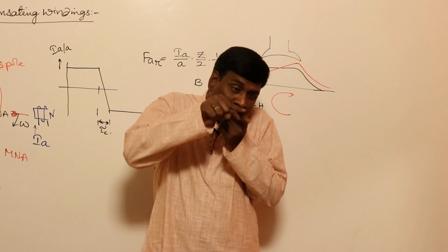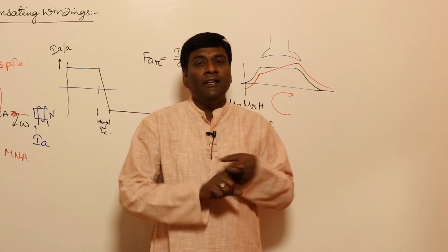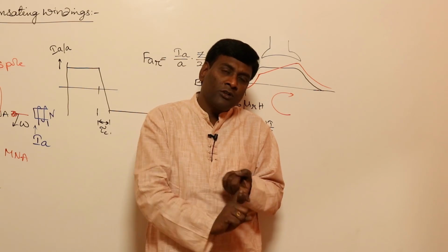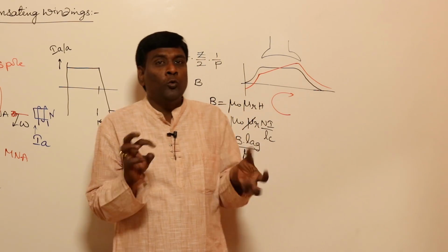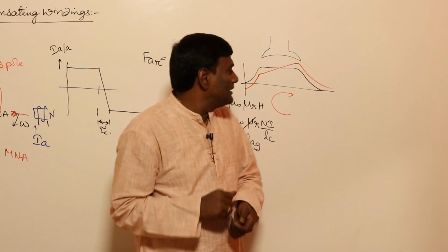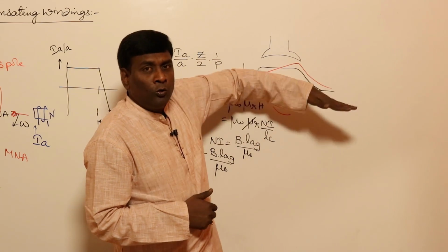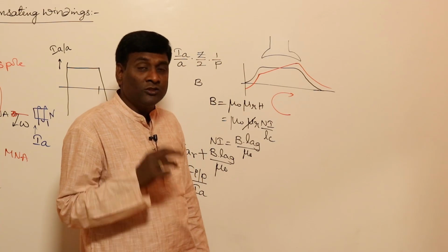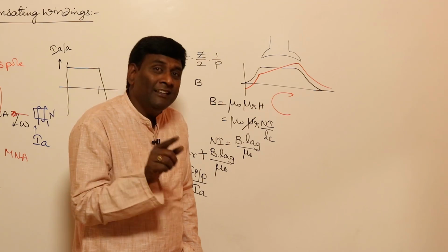But who will maintain a small air gap? Nobody will maintain it. He will short circuit, again he will open circuit, again he will start welding at full load, short circuit, open circuit, full load. So load variations are going to be tremendous. Under that condition, flux density goes no load, full load, no load, full load. Because of this variation of flux density, we are going to get statically induced voltages.